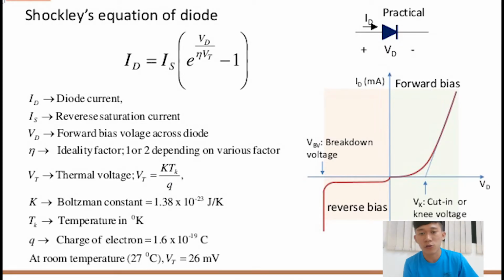Okay, this is because PN junction diode parameters like reverse saturation current, bias current, reverse breakdown voltage and barrier voltage are dependent on temperature. The rise in temperature generates more electron hole pairs, thus conductivity increases and thus increase in current. Therefore, if we kept the voltage constant, as we increase temperature, the current also increases.